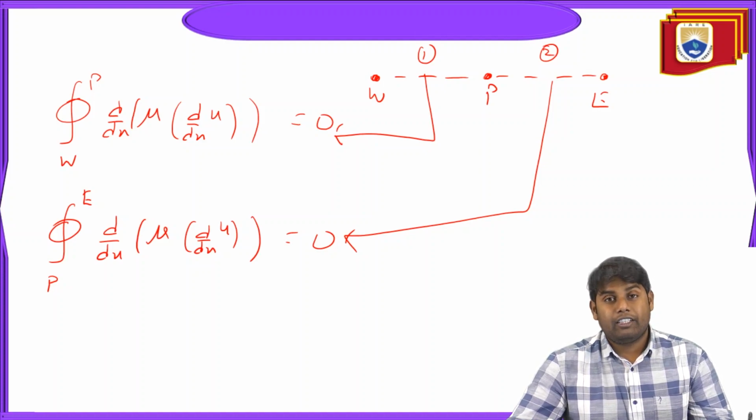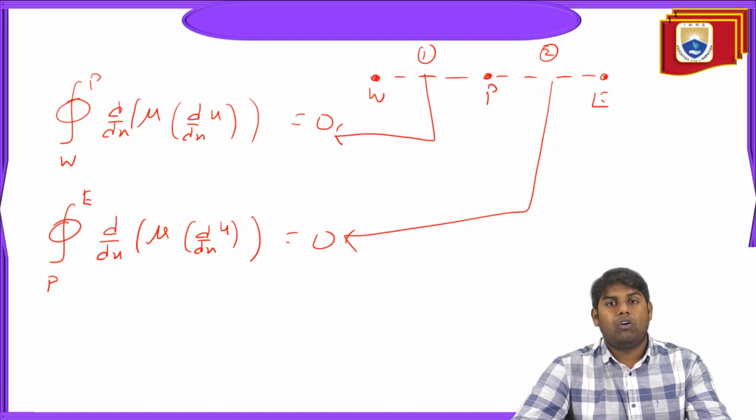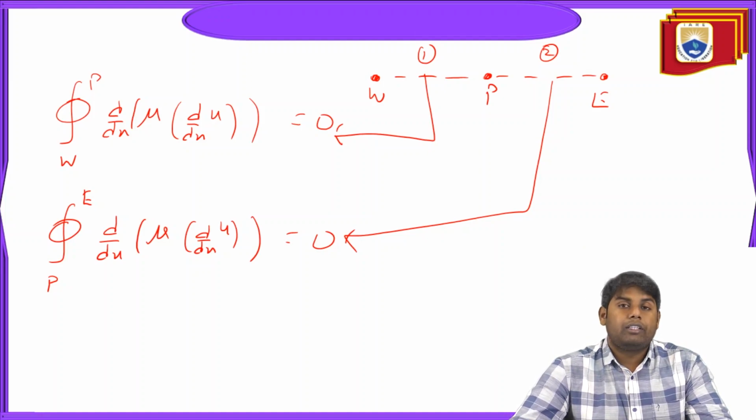For the finite difference method, we took the grid point, and at the grid point we took the Taylor series expansion, in which we neglect some terms. Here there is nothing like neglecting terms. Whatever terms we have, we do the volume, line or area integral. So this is the basic insight of the finite volume method.